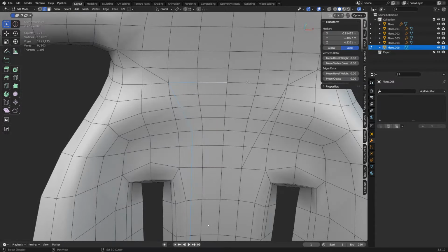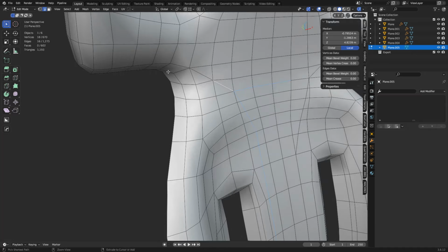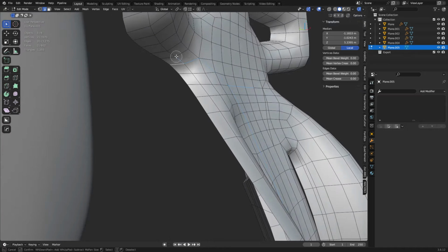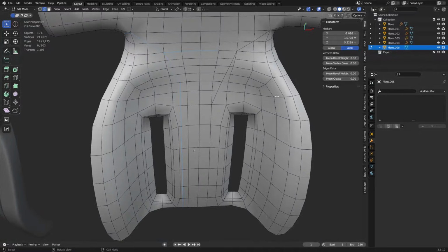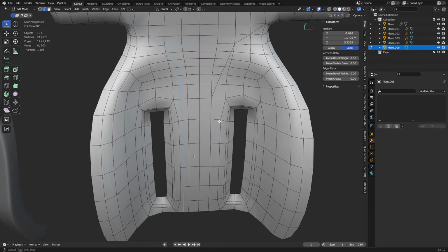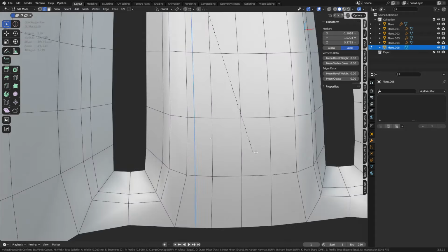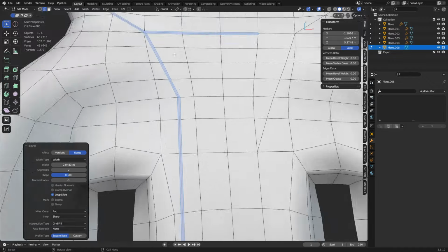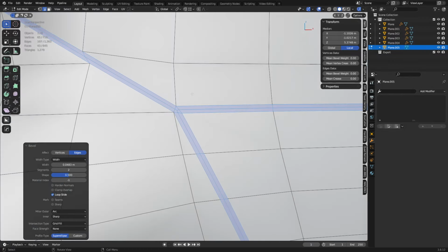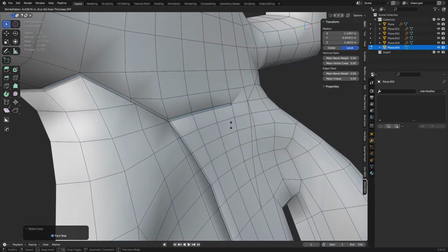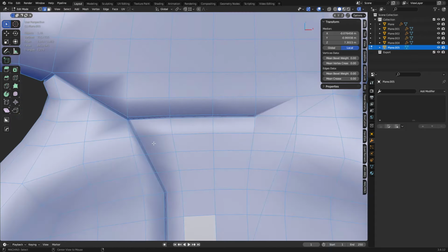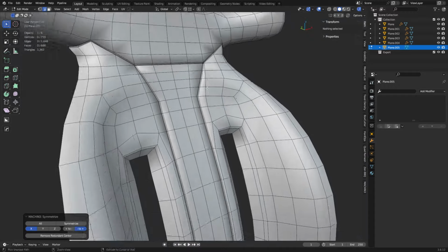Okay. Notice the knife tool selects it still. That's nice. I like that. Right. So there, we got this going. And I'm not worried about the other side because we're going to do a symmetrize with Mesh Machine there. But basically, you bevel, mouse wheel up once. So you have 3 edges. Okay. Control number pad minus and select less. And now you can do like an Alt S and push these in a little bit if you wanted to. Okay. When I symmetrize this, it'll be cut up like this now.